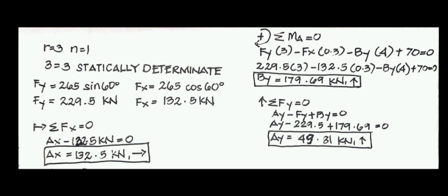This is statically determinate, meaning we can use the three equations of equilibrium, which are the summation of forces horizontal equal to 0, the summation of forces vertical equal to 0, and the summation of moment equal to 0, in order for us to solve for AX, AY, and BY.